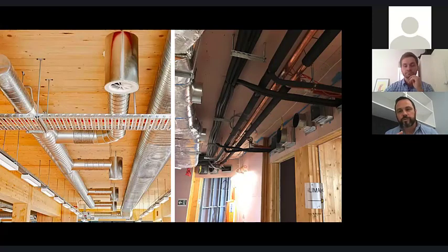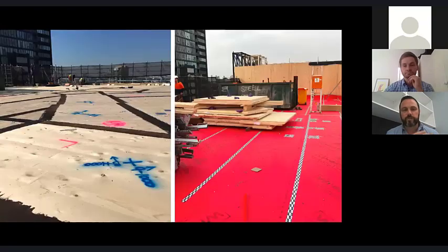And what that also links to is the need to provide temporary waterproofing to your deck above, when you start this fit out. So there is a possibility of putting your services in with an exposed soffit underneath, and water can still travel through. Obviously you want it to be minimal, but with the plasterboard, you really need to stop a large percentage of the water, because the plasterboard really struggles to manage the moisture, and water can get trapped between the timber and the plasterboard.